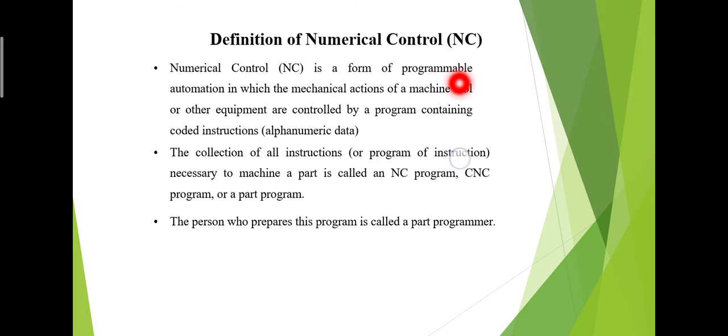to many reasons. The first one is reduced fixturization, because positioning of tools with respect to the workpiece is done by the NC program rather than by fixtures or jigs. It also reduces non-productive time and human error. NC machine centers can perform the machining operations of several conventional machines simultaneously, thus reducing the number of machines required to manufacture a product, and also the lead time to manufacture.